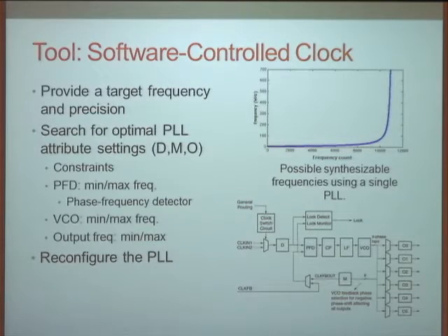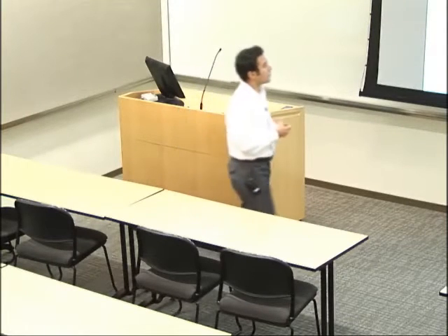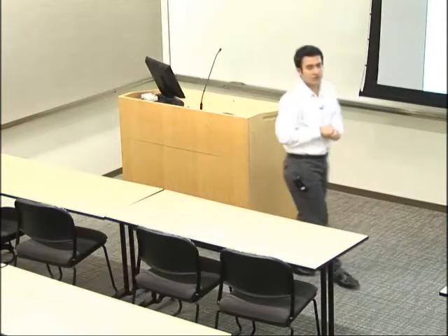So basically I have to read the frequency in reverse. I want 400, how do I get 400? Can I qualify? So the thing is that if you need a low frequency, probably one PLL would be enough. But if you want an accurate high frequency, there's a chance that you don't hit that frequency in the upper curve. So you need a second PLL for that.